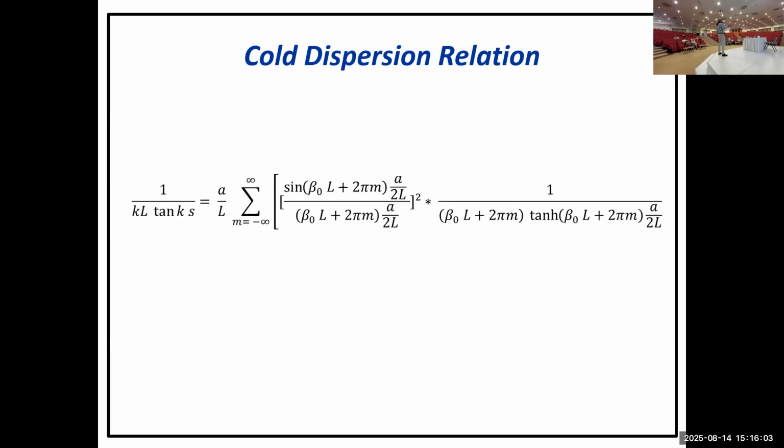So now this is the dispersion curve or dispersion relation for all modes and for all what they call harmonics, basically. Since you are talking about Fourier expansion, you have harmonics because of the summation, right? And this is going to be the 0th harmonic or -1 harmonic and so on and so forth. And these are different modes. One of these modes will be resonant with the electron beam. You're going to choose one of them in design.